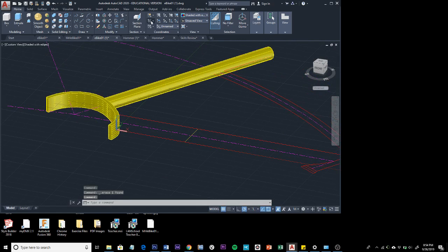So I'm going to click this button here. Y I think is the default, but we're going to go ahead and choose it anyway to make sure it's rotating on Y. And again, you can either use the dotted green line to snap, or just click enter to accept the default. Now our drawing plane is snapped to right here where the end point of the line was.